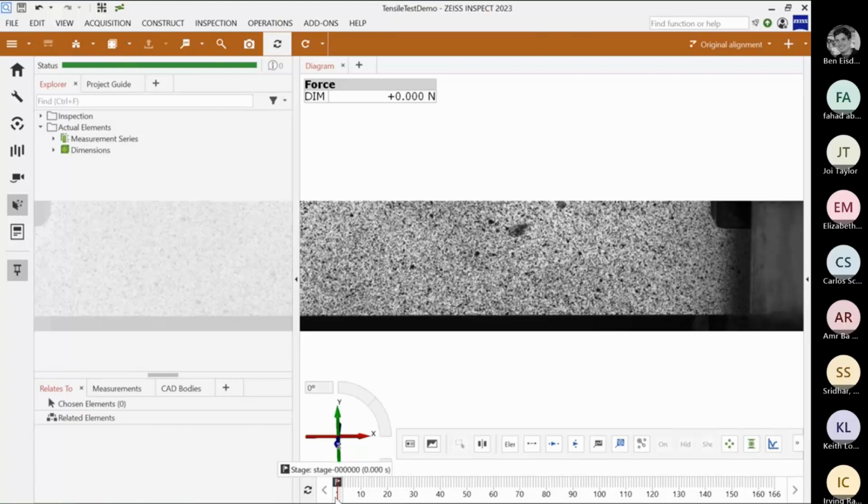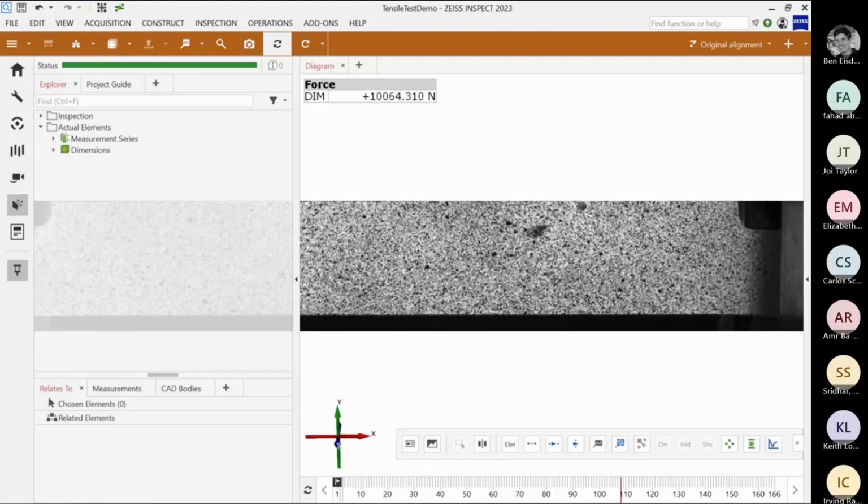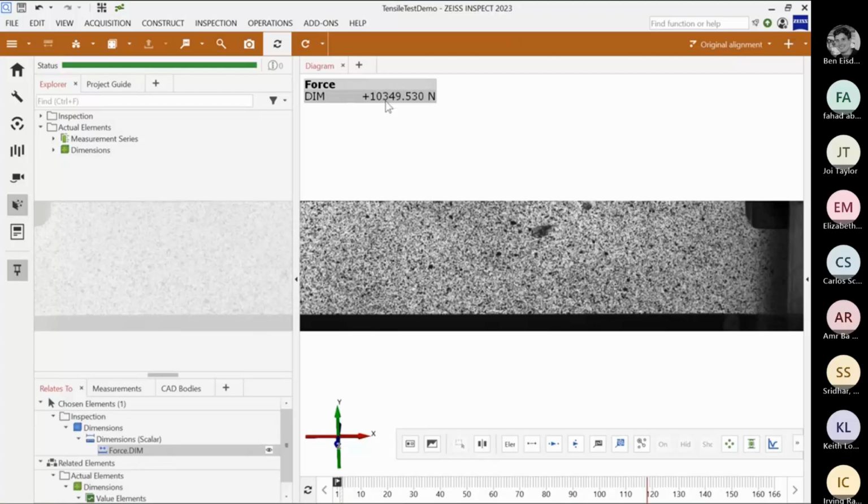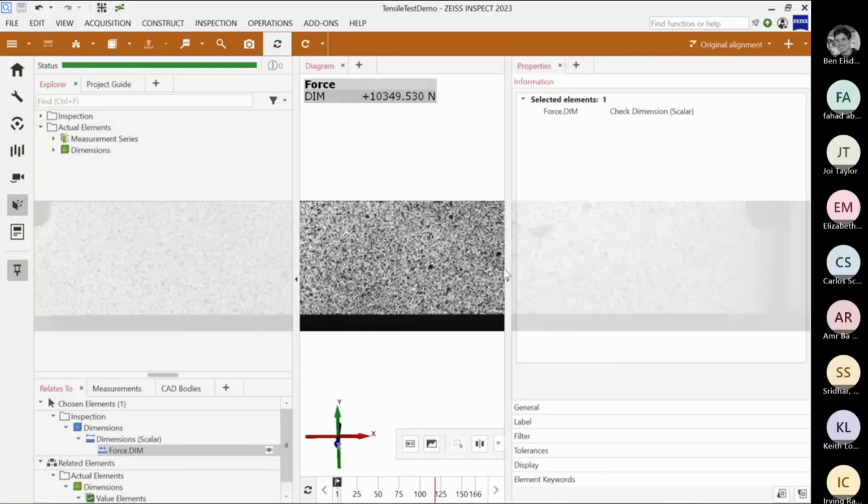And keep in mind, we do have versions of this tensile testing suite that are even more automated. When we have the live feedback of a universal testing machine with the live force input, we can run very many samples in a row at operator level interaction and automated reporting. With the tensile testing script, though, we can come back and reanalyze or analyze data just as long as we have the 3D image series of the tensile pull and a force channel as we do in this project.